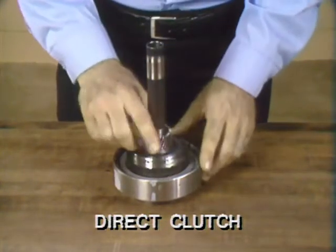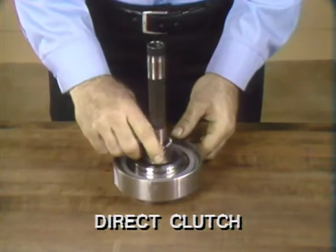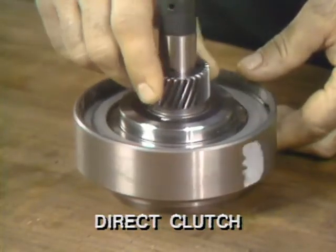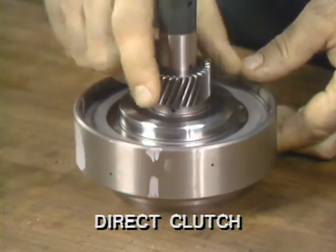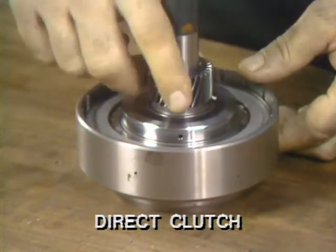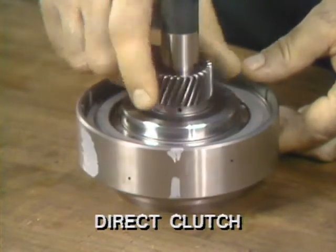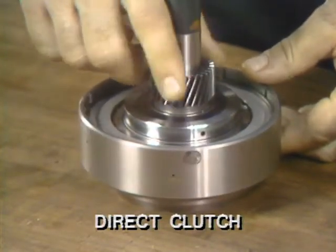Now, if the direct clutch is applied, there is no freewheeling. The turbine shaft continues to drive the low reverse sun gear, but the sun gear cannot overrun the turbine shaft. The direct clutch locks the shaft and sun gear together, and this gives us engine braking in manual low or reverse gear.